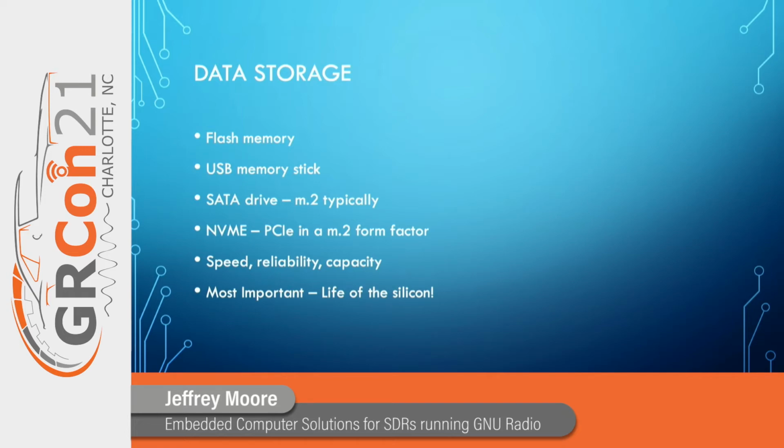The speed, the reliability, the capacity are all an issue. But most importantly, in an embedded environment, it's the life of the silicon. All flash drives, NAND drives, all these semiconductor types of memory have limited lifetime. You can write to them only a certain number of times, measured in the thousands or tens of thousands. So you have to architect your system in a way so that you minimize doing that. Now, many drives will have extra space on the drive and will intelligently skirt around areas that have been written to too many times and start to wear out, and that's all invisible to you.